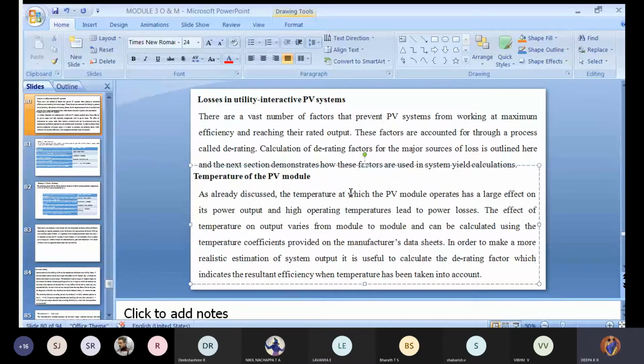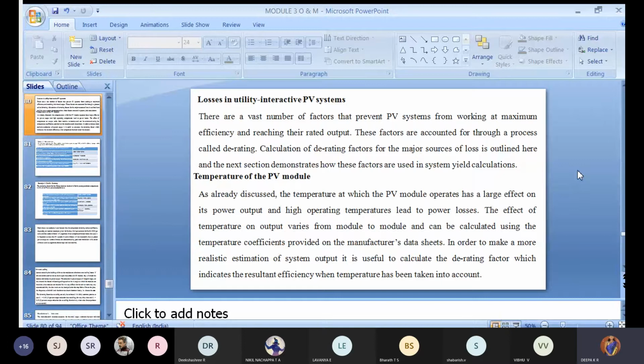So till now, whatever we did, it is like a huge portion where PV installation will be carried out. So now we have to think about the derating factors which are affecting the power output of a system. We discussed that temperature is one of the main phenomena which is going to affect your PV output, because if your cells are too hot because of heat loss, your output will be reduced. Similarly, in the colder region, if the temperature is less, of course the output looks good, but other parameters like dirt accumulation or salt accumulation and of course snow accumulation are going to create other problems like corrosion. In that way, we'll find out which factors are affecting the system.